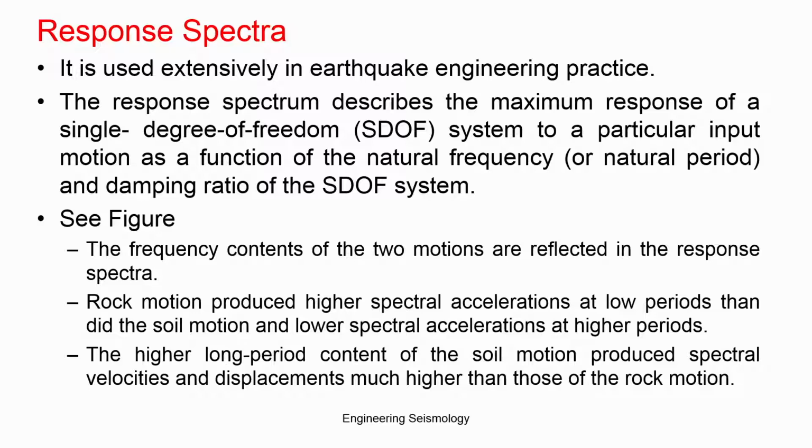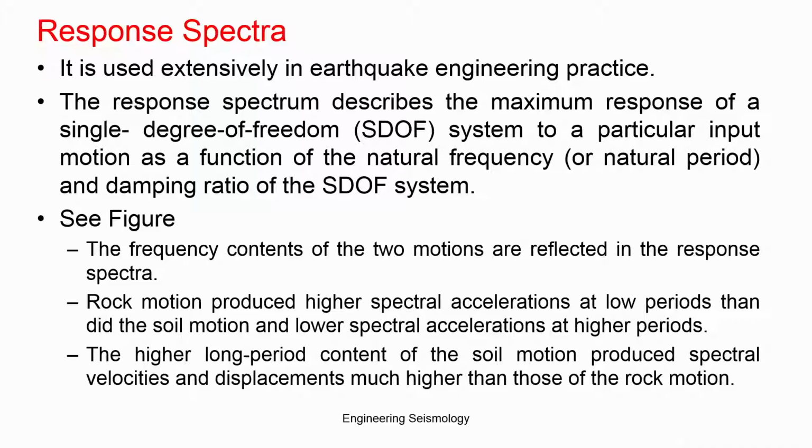The spectrum is basically a plot of frequency versus amplitude. The frequency can also be plotted as the natural frequency or natural period by taking the inverse. So, it is basically the response of something plotted as a spectrum, which is called a response spectrum. It is used extensively in earthquake engineering practice.